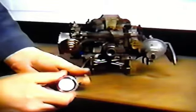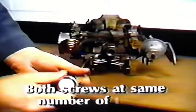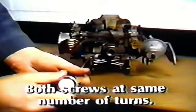The other screw gives 3.5. This discrepancy between the number of turns is a sure sign that the carb was not properly balanced. Both mixture screws need to be at the same number of turns for a balanced carb.